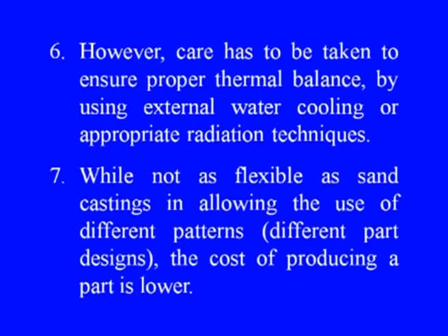So, the cavity does not need to be expanded as much as in the sand castings. However, care has to be taken to ensure proper thermal balance by using external water cooling or appropriate radiation techniques.